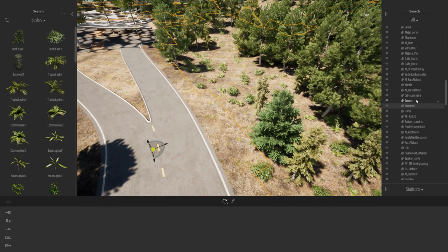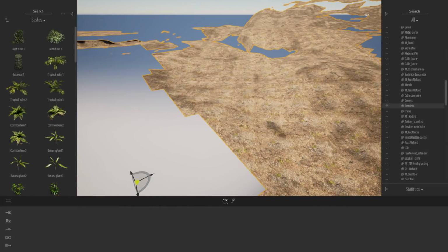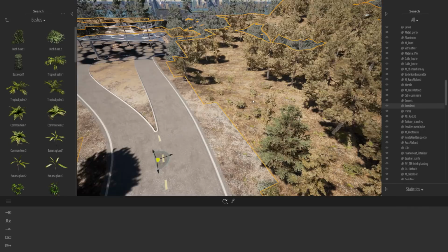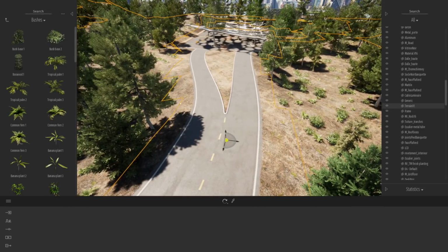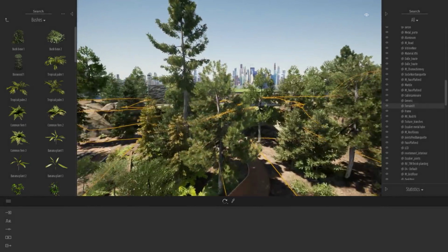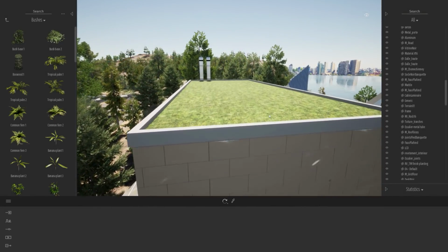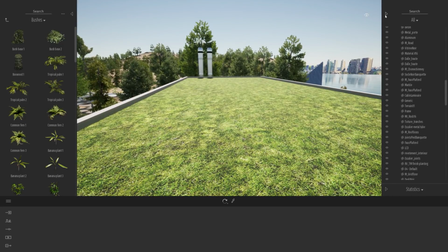And actually, what I did here, I selected the second geometry here on the side. Same thing here. Here is the look of my geometry. And I actually planted my trees just on this specific geometry and not on the first one that is below my road. So this way you can avoid having any object like vegetation that will be planted through the project. We can use this scatter tool to vegetalize large areas like I did here, but we can also use it on smaller areas like my roof over here.